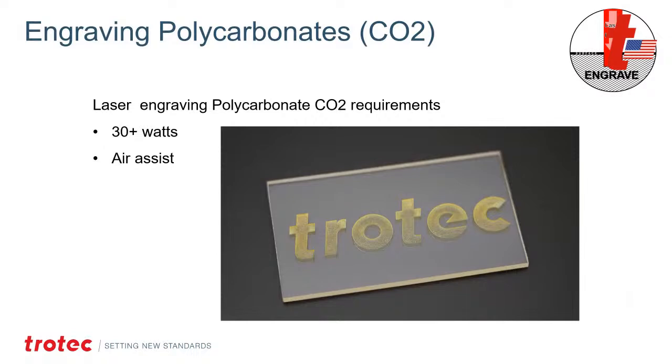Here's what the CO2 laser will look like when you engrave it. It tends to produce a yellowy looking effect from the CO2 laser. It doesn't require a lot of laser power, but I do recommend air assist when processing this material. It does produce depth into the material, but again, the quality is yellowy. It's not really visually desirable compared to the fiber laser, so just keep that in mind when understanding how this material is going to process. The sharpness of the characters and everything are good, but that yellowy contrast is typically a little less desirable, especially if you're doing a barcode or something. It's not going to work very well.